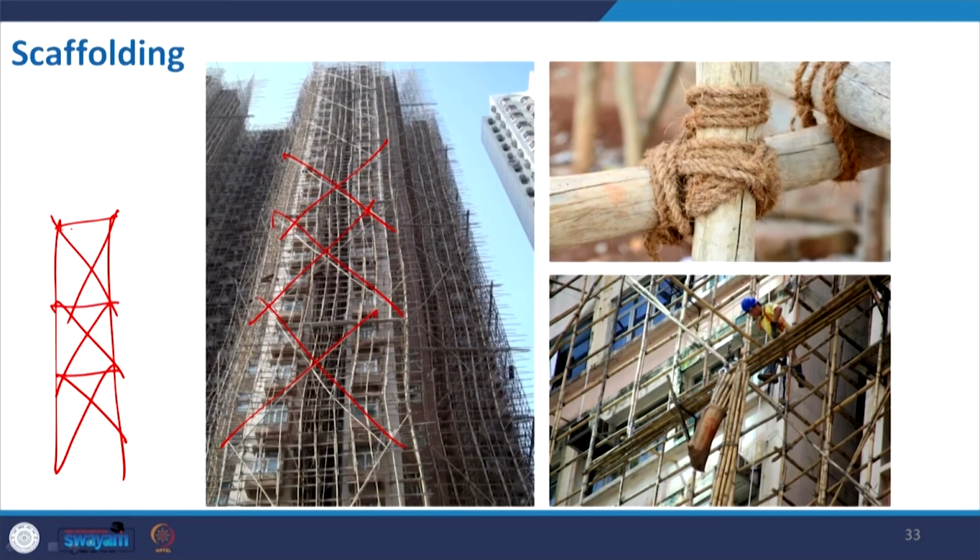There will be wind from different directions, so that may collapse. So, for that also in the structural arrangement we have to put some bracing, and you can see that due to that huge height and different platforms, and also it is not straight. So, compared to that, if you use steel members, then it will be more stable.